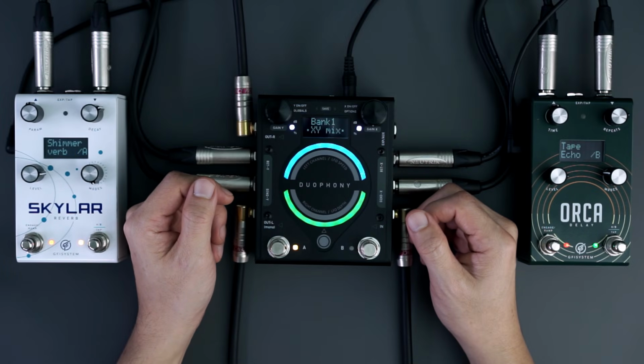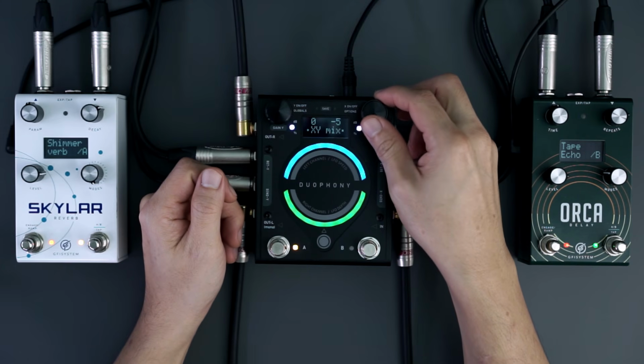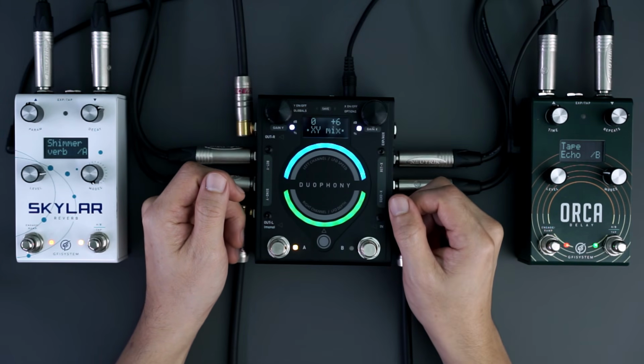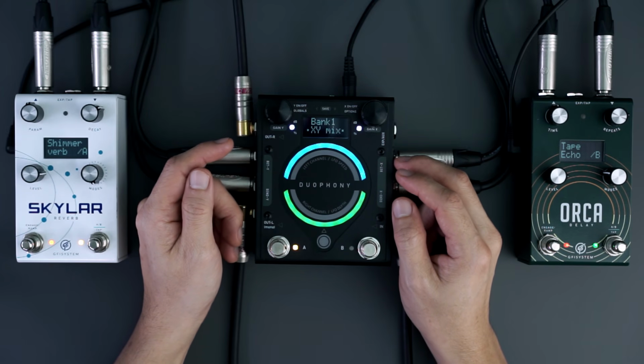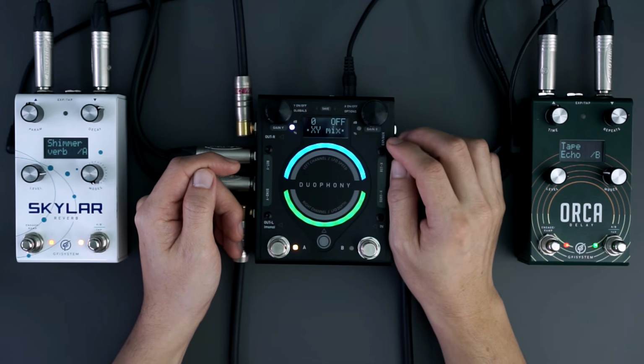Duophony provides individual gain control for loop X and loop Y. The gain control goes from -infinity dB or mute to +6 dB. You can use the gain control to fine-tune the overall volume balances across presets or between engage state and bypass state. Note that the gain knobs are also buttons that you can push.